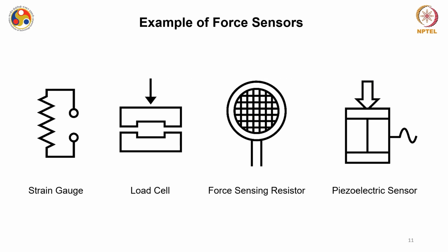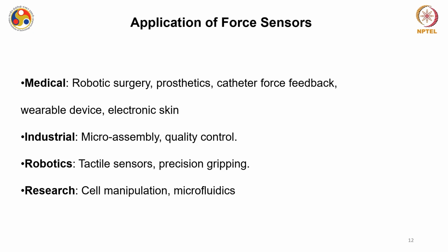There can be a number of force sensors at both macro level and micro level. They can be based on a simple strain gauge, which also leads to load cells. You have force sensing resistors, piezoelectric sensors and so on. Applications of these micro force sensors are in medical, as I have just mentioned, in robotic surgery, prosthetics, wearable devices, electronic skin.